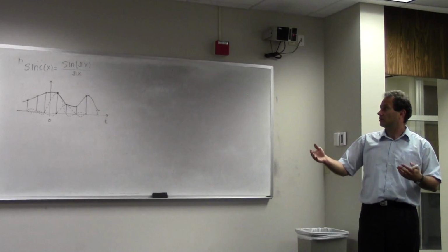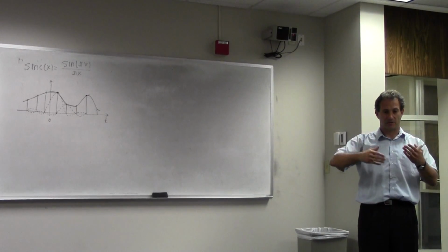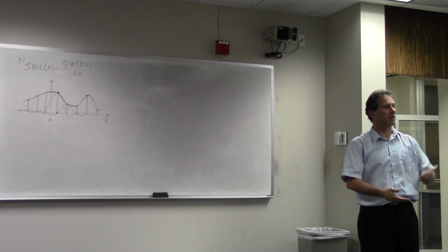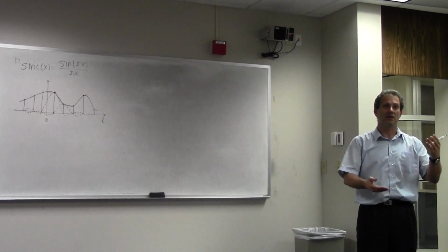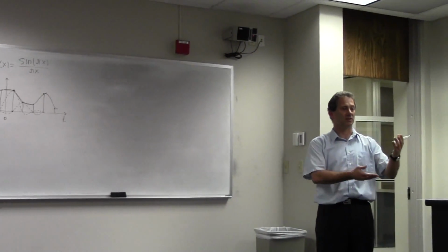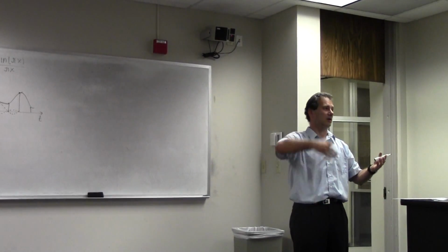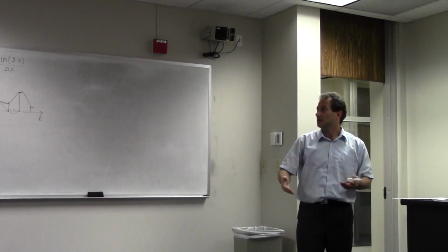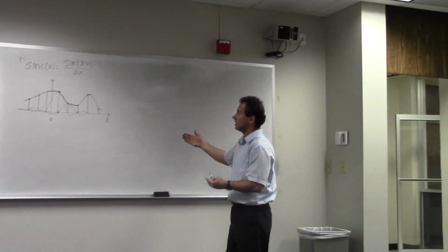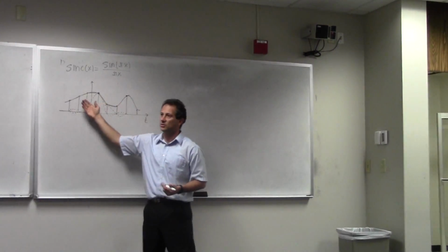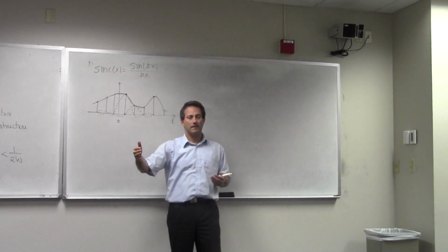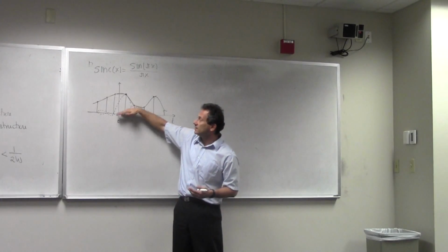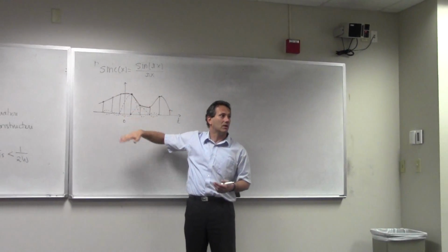In other words, we have to take care of the time, but we also have to take care of the magnitude, because the random process exists along two axes: along the t-axis and along the amplitude axis. Sampling tells us, okay, you don't need all of these points. You can have the points at discrete time increments. But it says nothing about the y-axis.